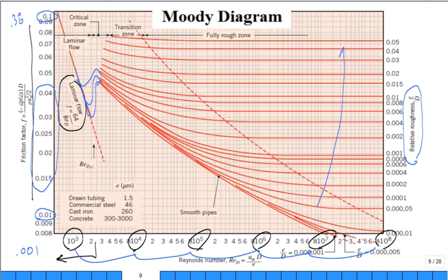Isn't this for a rougher pipe? Where's the smoothest of the smooth pipe? The lowest curve on this Moody diagram. So somehow you're transitioning, and probably for a rougher pipe, it's going to stop being laminar before 2300 and start that transition, because those bumps on the sidewall will trip it to be turbulent.